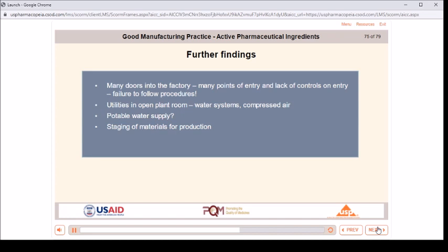There was no formal flushing procedure following maintenance. Some water was run away to waste, but it was not proceduralized. 3. The local reservoir supplying potable water was within a few miles and downwind of the penicillin plant. It was not established whether there was a risk to the potable water supply. This was outside the remit of the company. Should this have been reported to the government environmental agency?